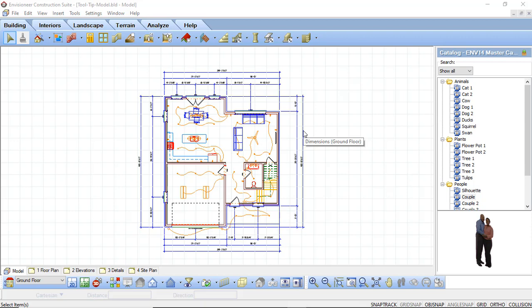Creating an electrical plan in Envisioneer is easy to do, as you're going to use the model you've already created and then add in your lights, switches, outlets, and wiring paths. Then in your worksheet you will use the View Filter option to isolate the desired elements you want to show.